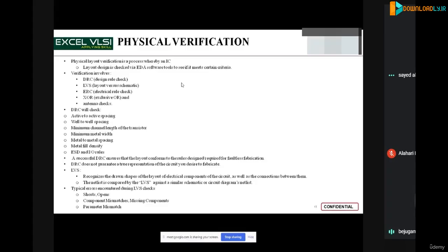That means wherever the power cell is connected to my gate, whatever input voltage you pass through that net or interconnect can cause an issue to my gate. So those checks are done in ESD, electrostatic discharge, where you check for the discharge of the voltage, and the IO rules check whether it is coming from the input voltage or not. So is it clear? Yes, yes.